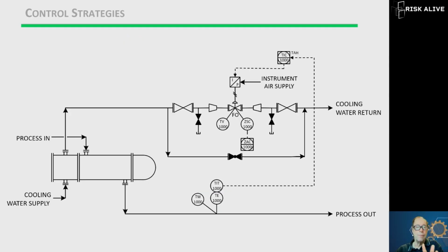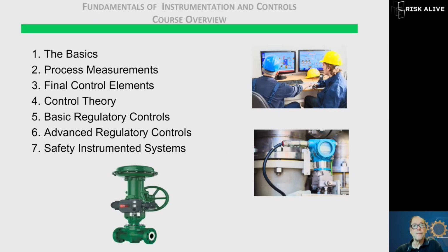So once we've done that, then we go back and look at some loops on the P&ID, right? And now we know what's inside this little black box here, what it's actually doing. And we look at different failure modes, what happens when it fails, right? Does that valve here is shown as fail open, right? So it's going to fail open, but other things might happen, right? Might get stuck. We might get some bad values in our measurement. So we need to talk about those types of failure modes as well as talking about how this loop is going to work.